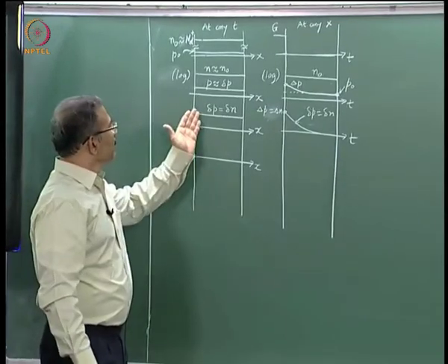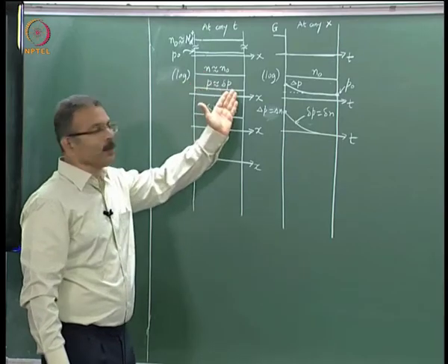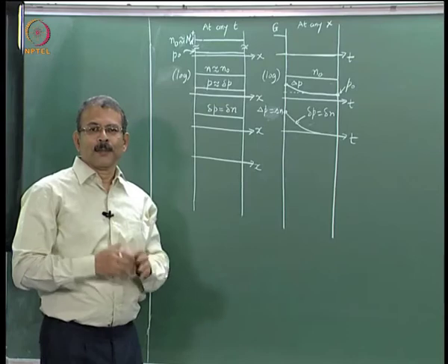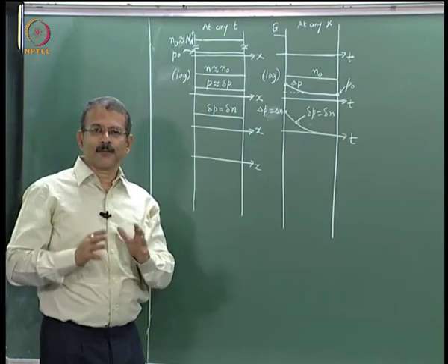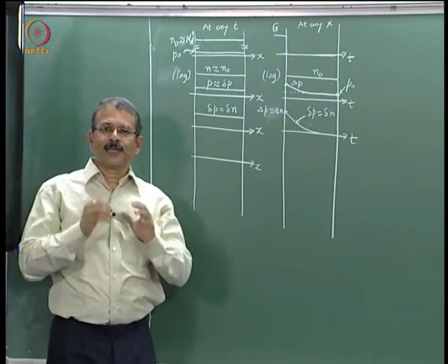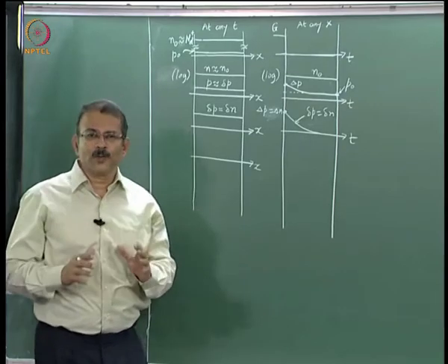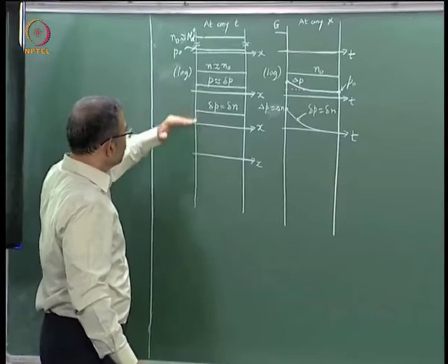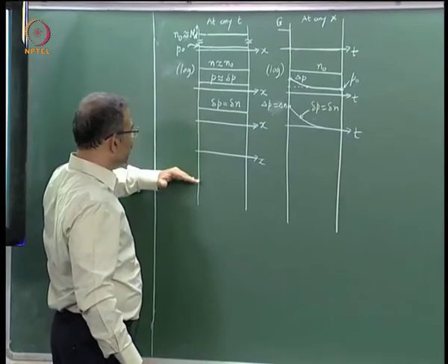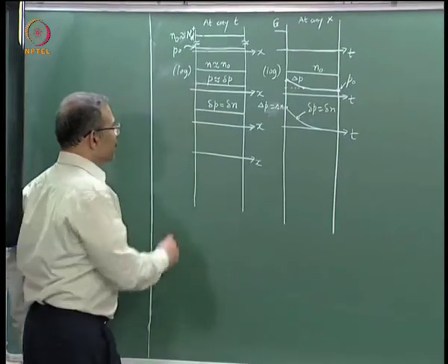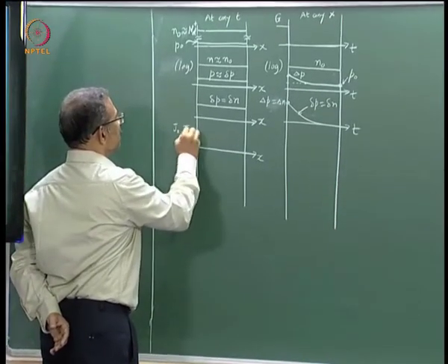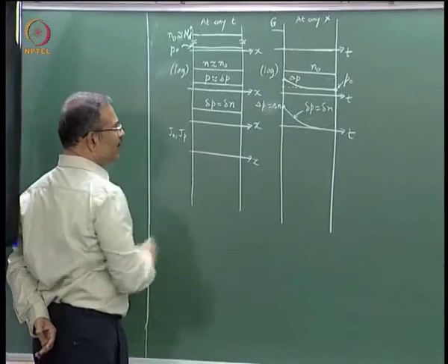If the carrier concentrations are uniform throughout the volume, you know that there is no diffusion current, but Jn and Jp can contain drift current also. Now how do you know whether there is a drift current or not? You need to know whether there is an electric field. So as of now, unless we know the electric field, we cannot plot Jn and Jp. So let us leave this for the present.